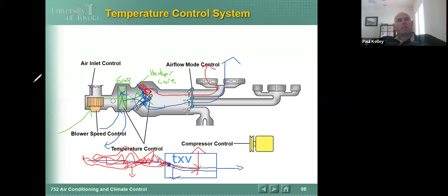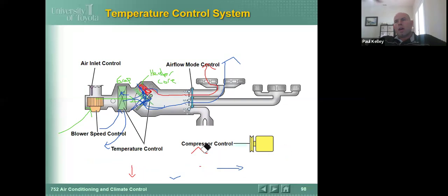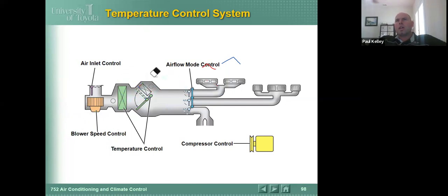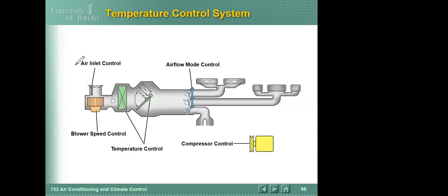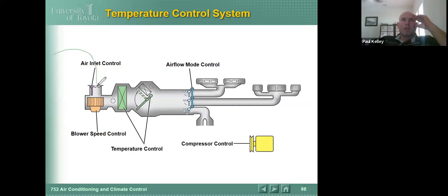And then for us, let's get more into how we're going to heat and cool the air. So let's assume from here on out that the heater core is hot and that the evaporator is working properly. Let's start with the air that comes in. Give me a volunteer. Is the air recirculate or is the air fresh air? You guys let me know. What is it going to be? Fresh air. Fresh air, here you go. This is coming from under the cowl, going into the blower motor.